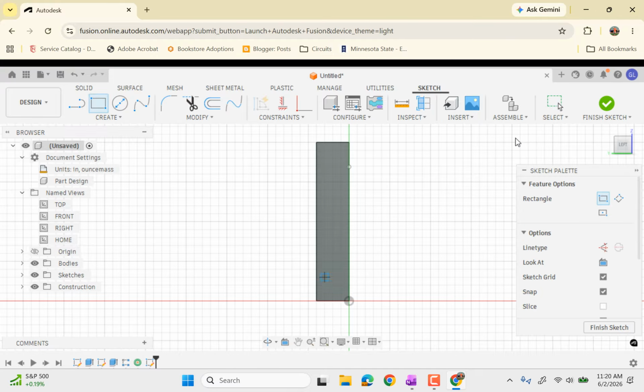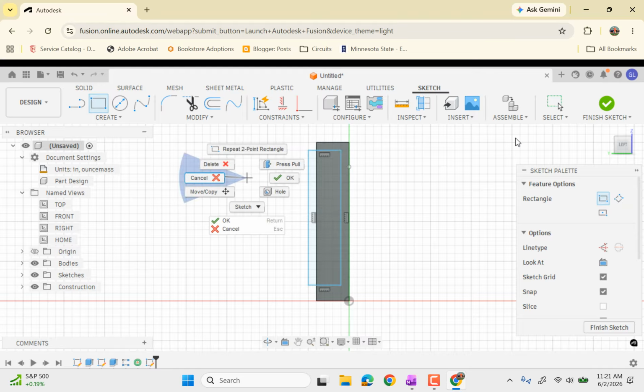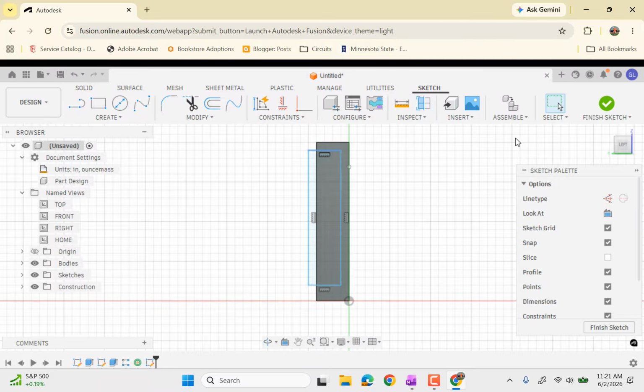And then I'll use the rectangle tool. And this is a place where I'm going to make this rectangle a really crazy shape to keep it from guessing at how big I want everything to be, so that I can specify it myself. The way that it guesses at sizes you want often causes more problems than it's worth.